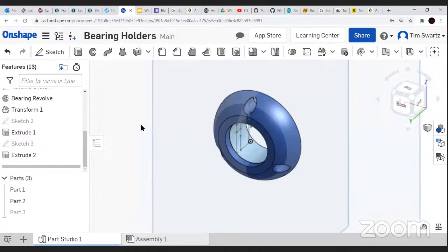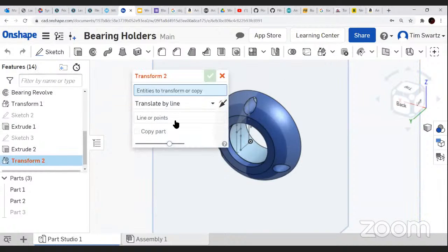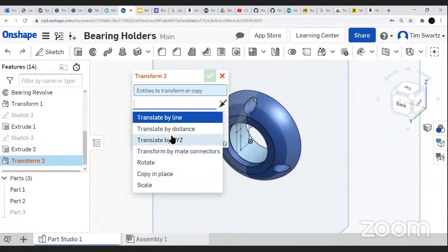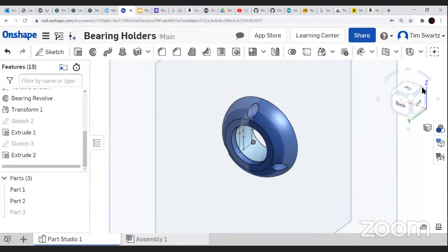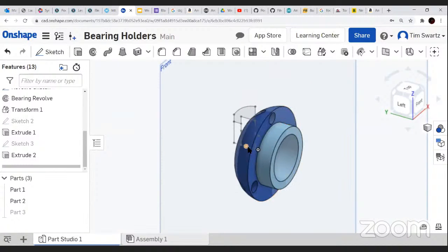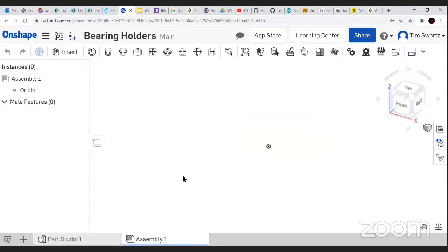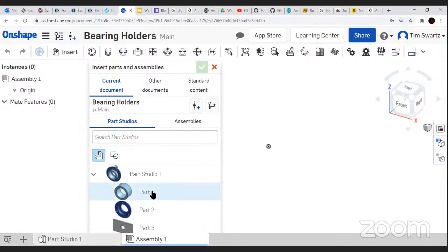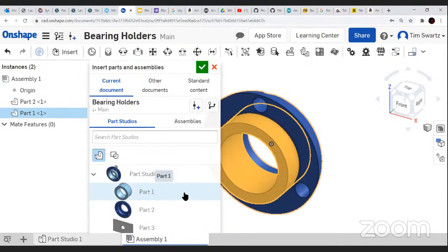You'll probably just have to do it by XYZ and moving to align it. But it doesn't really matter because everything that we've modeled, if you have all those same dimensions, it should be just fine. And we're not modeling this now because right now we're in the part space. We'll go over to the assembly space, and you can put all sorts of stuff in here. So I can go in and grab this part and that part, and we can move them all around in there. And that's how we're actually going to assemble this model.